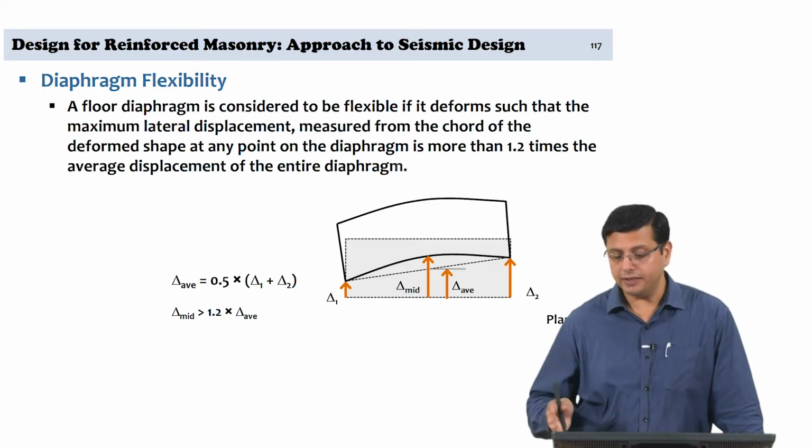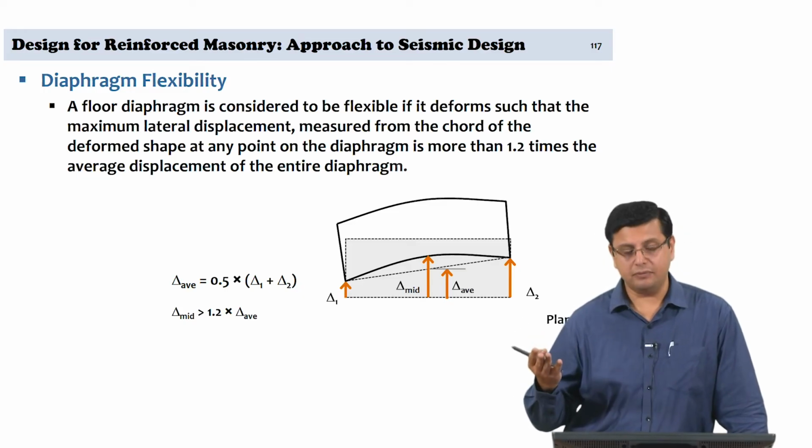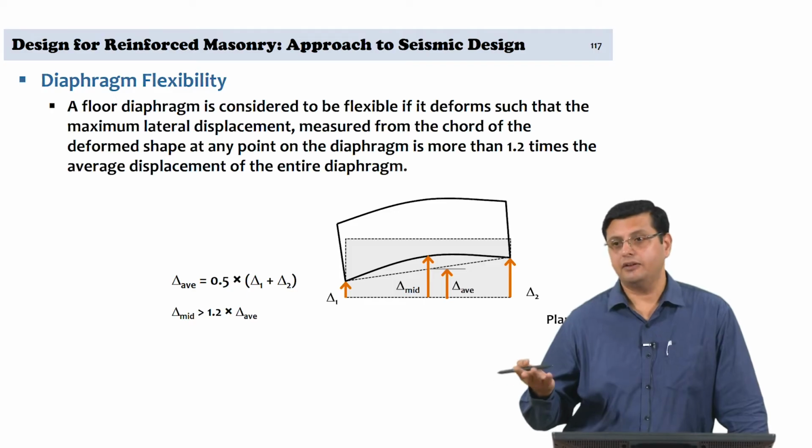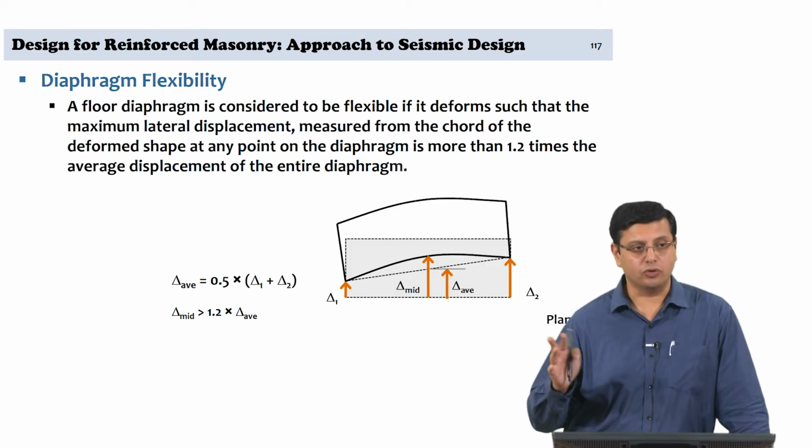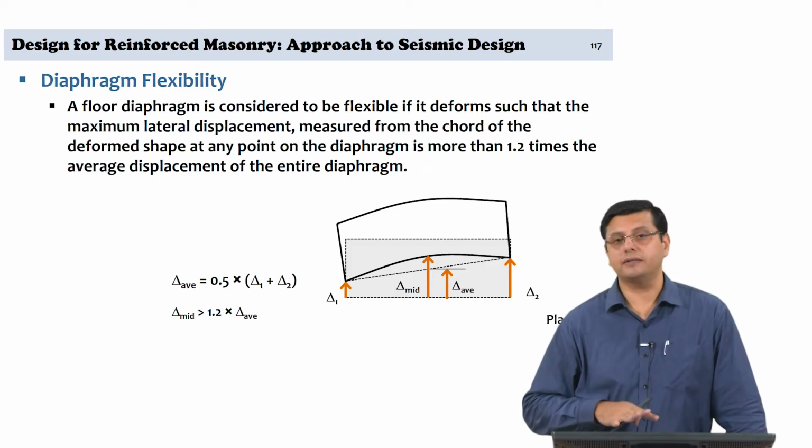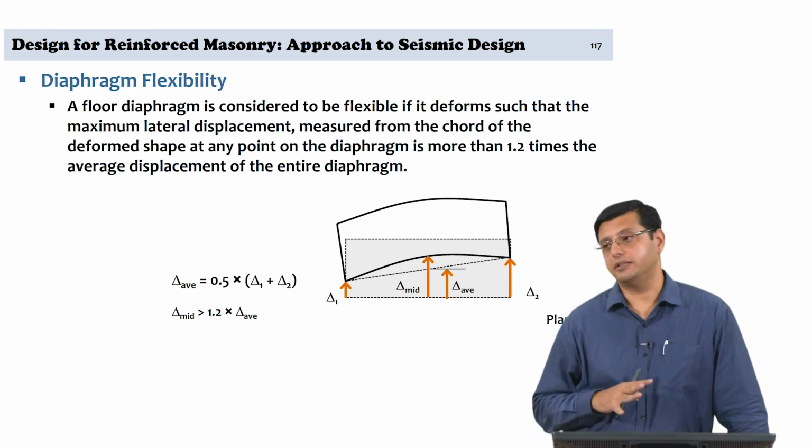However, when you are dealing with examples that we had seen at the beginning of this lecture, such as Madras terrace floor slabs or jack arch floor slabs, it may not respect the requirement for a rigid diaphragm action.